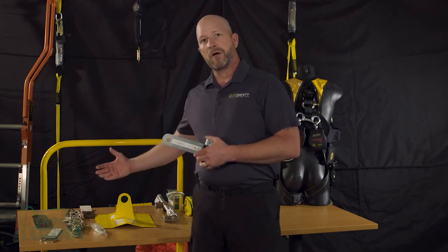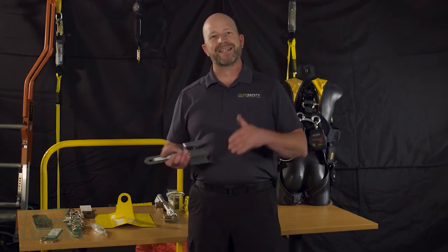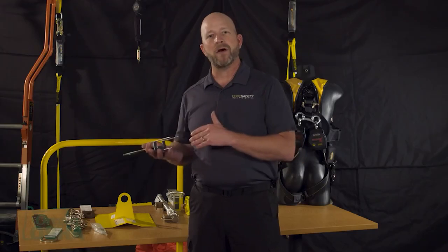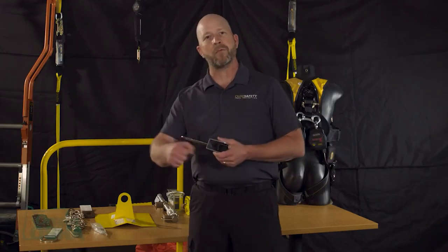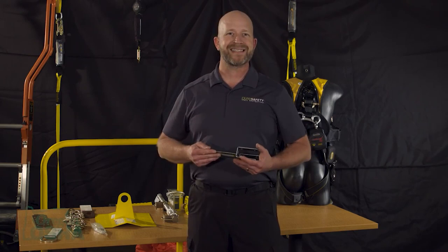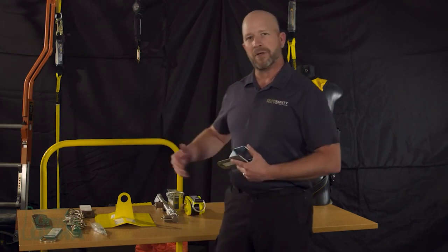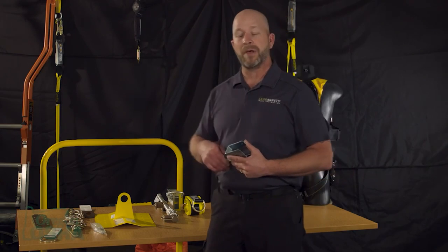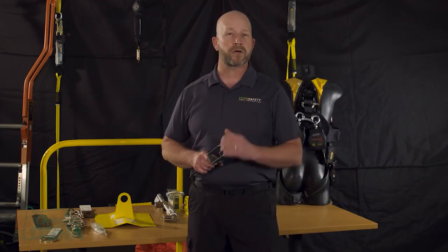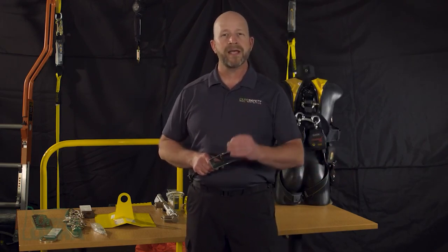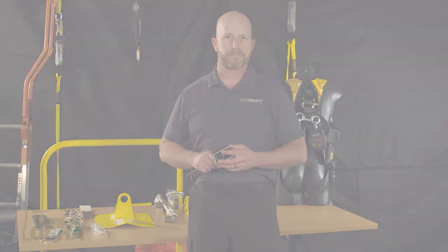If I'm attached with an anchor such as this, and it's only attached to 26 gauge, and the manufacturer requires 12 gauge, depending on what it might be, then we know that it's not attached to something that will withstand the forces that it's designed to apply to the structure. So always be sure, not only do we select the right tool for the job, that we install and assure our workers install it the appropriate way in the appropriate place.